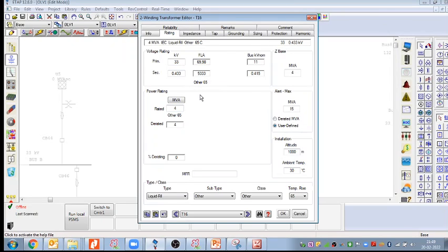So yeah, the point is clear. The concept is clear. If this much current rating is available, we can go with 4 MVA. If any vendor is ready to supply 6667, then we can go to this one. But as per my knowledge, a 6667 or 7000 ampere breaker is not available in the market for 433 voltage.